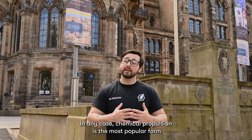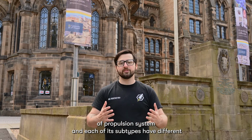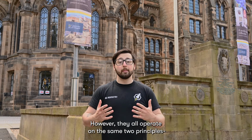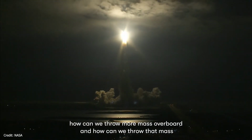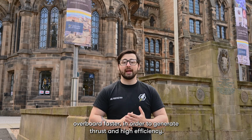In any case, chemical propulsion is the most popular form of propulsion system, and each of its subtypes have different benefits and drawbacks to how they operate. However, they all operate on the same two principles. How can we throw more mass overboard, and how can we throw that mass overboard faster in order to generate thrust and high efficiency?